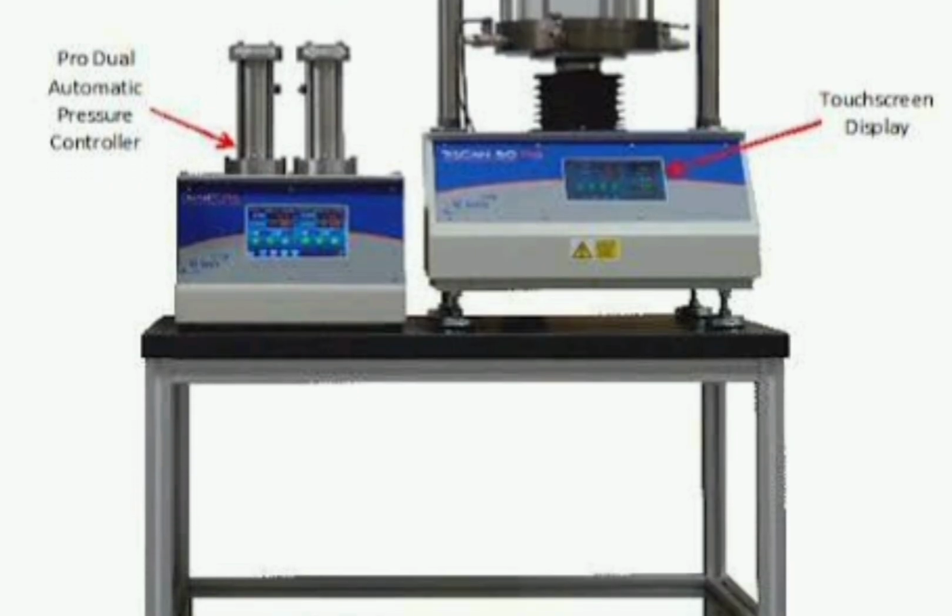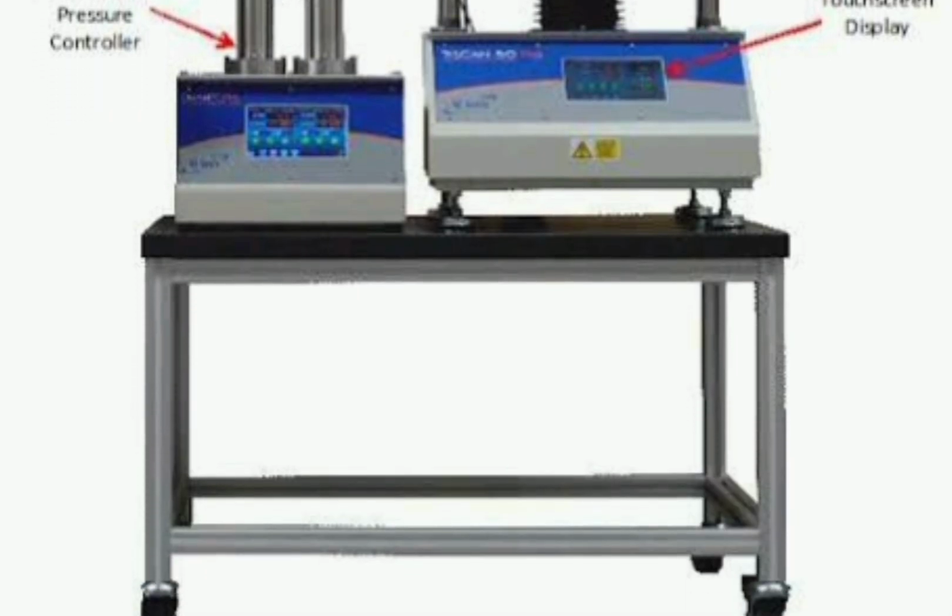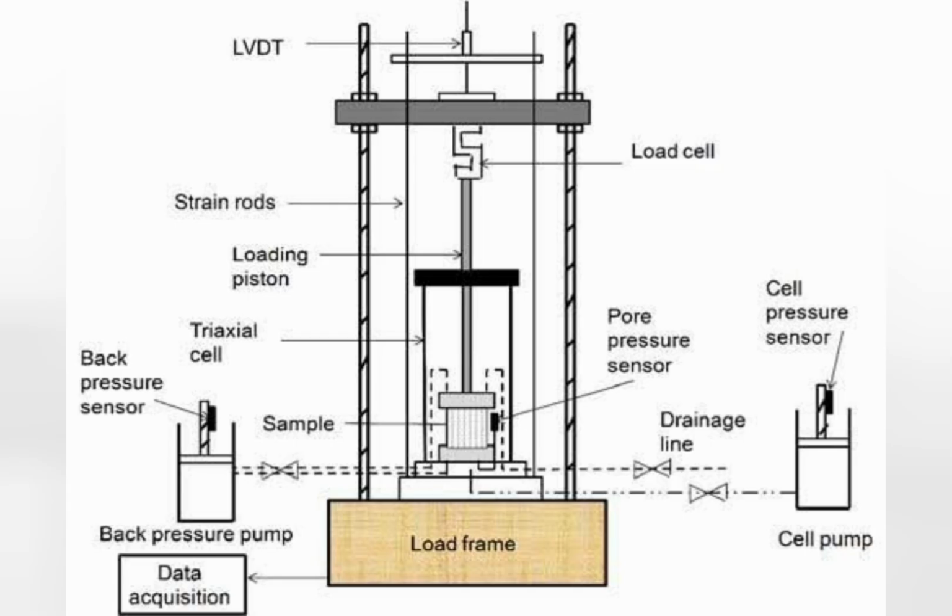There are different types of triaxial tests that simulate different field conditions, like a consolidated drained test for long-term slope stability or an unconsolidated undrained test for the immediate stability of a clay layer after excavation. The results give us a much more reliable and detailed understanding of the soil's strength envelope, which is directly input into software for slope stability analysis and foundation-bearing capacity calculations.